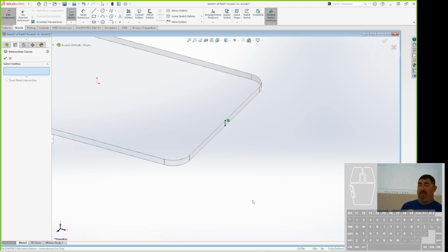And so this is one of the times that I use sweeps. You notice we haven't used sweeps kind of at all. In the classes we talked about them, but we really didn't use them a lot. But we want to follow the entire perimeter of this object. That's a perfect time for a sweep.